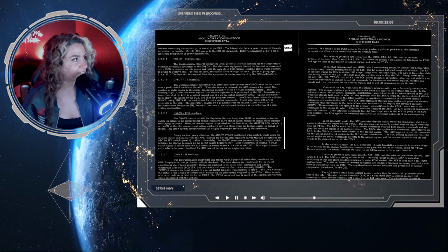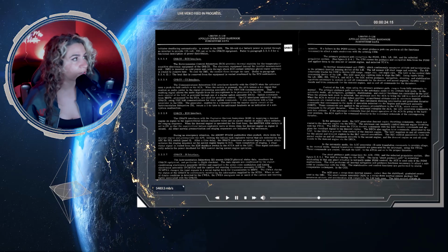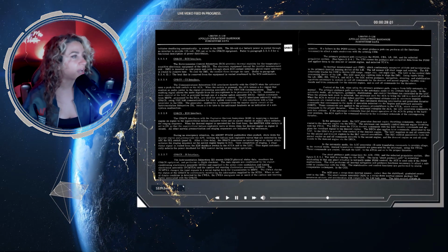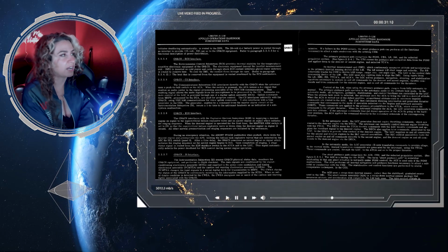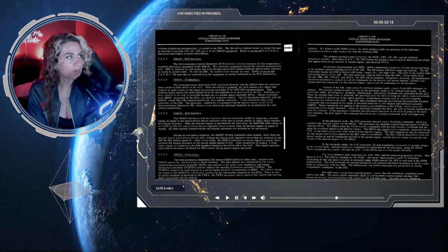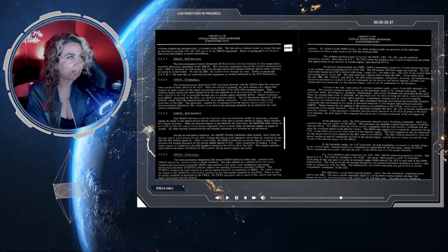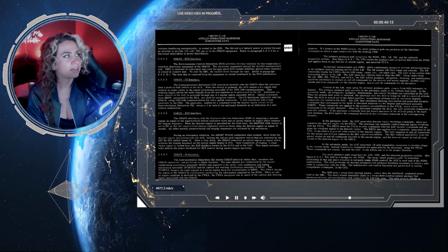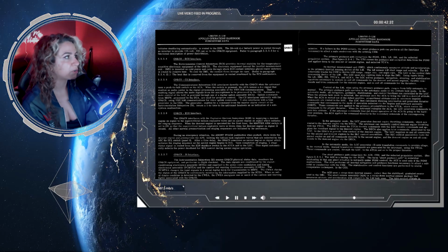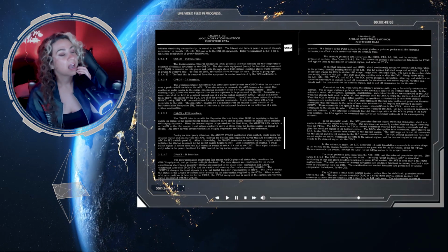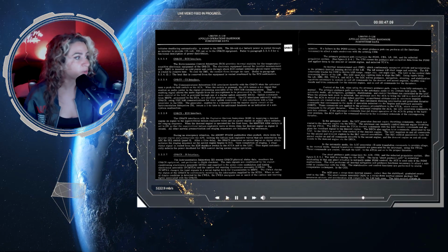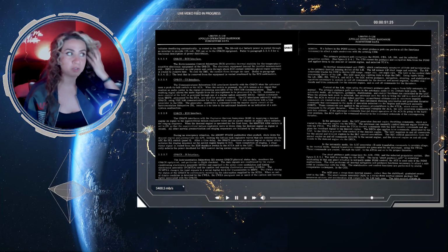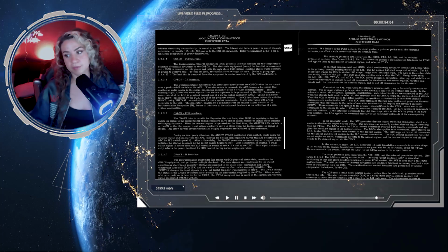Which initiates dead facing automatically is routed to the EPS. The 28-volt DC battery power is routed through an inverter to provide 115-volt, 400 CPS AC to the GNNCS equipment. Please refer to paragraph 2.2.3.8 for a functional description of the power distribution. Wow. 2.2.3.8. We got some time, there's some ways to go before getting to 2.2.3.8, but we'll get there.